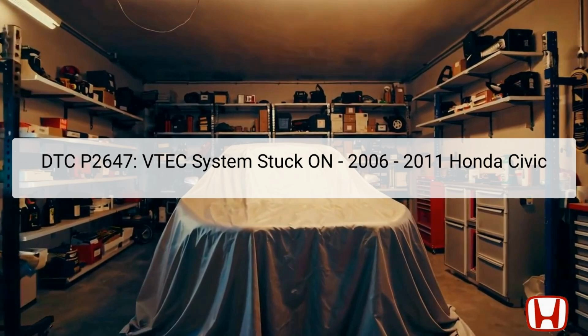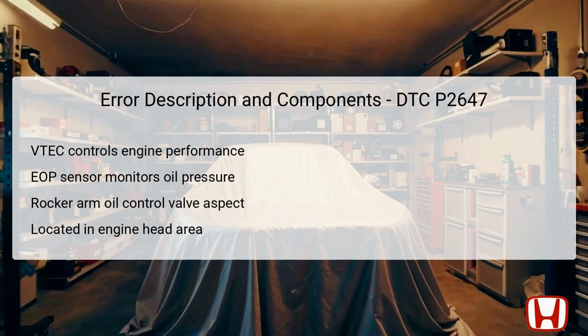This issue can arise due to malfunctioning components, inadequate oil supply, or electrical faults affecting communication with the engine control module (ECM). Understanding this DTC is crucial for both diagnosis and repair to ensure the overall health of the vehicle's engine system. The variable valve timing and lift electronic control (VTEC) system plays a critical role in enhancing engine performance, particularly in Honda Civic models from 2006 to 2011.